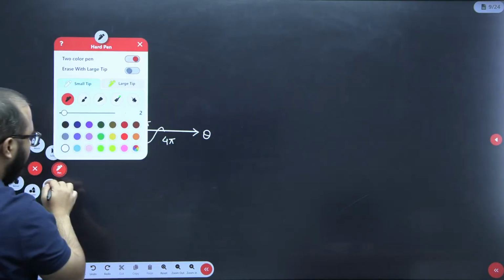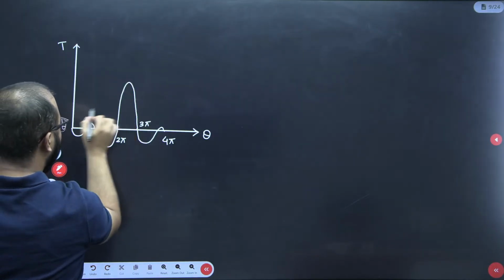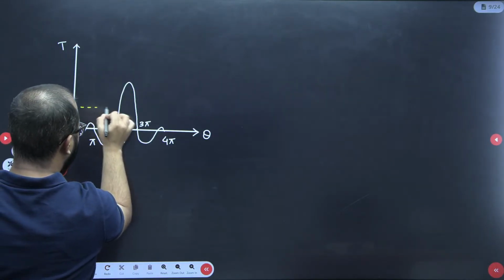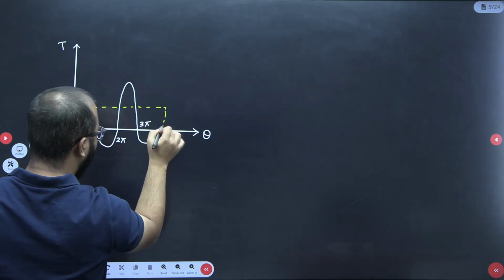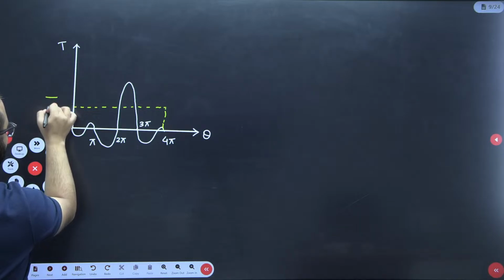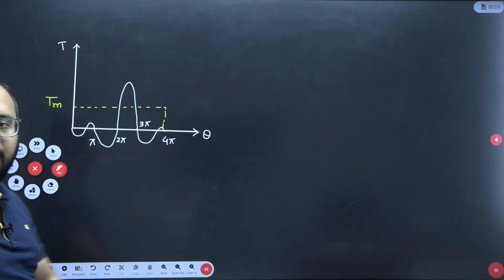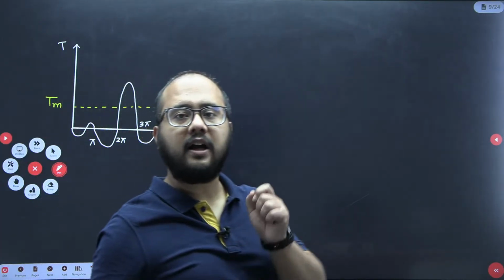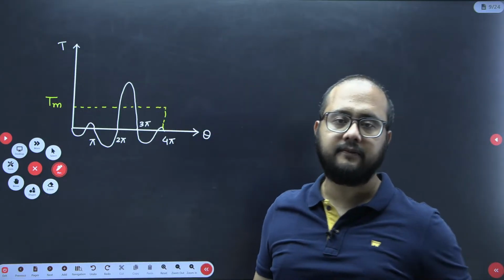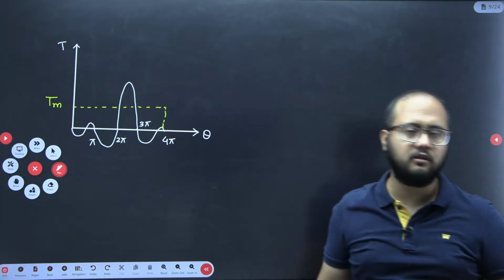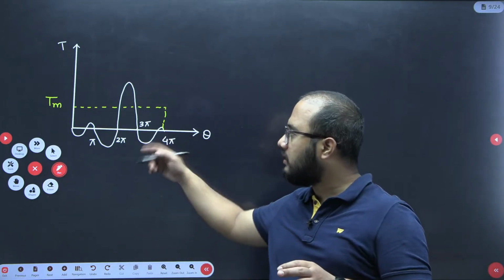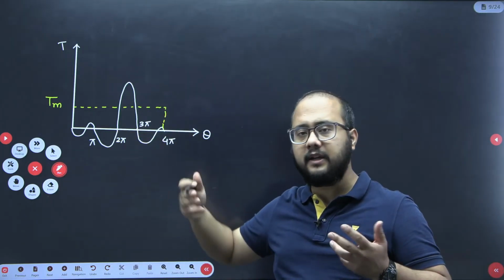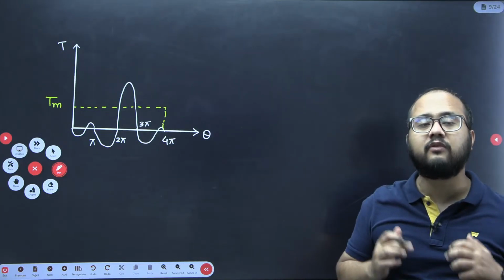Now here you need to understand that we have also mentioned the mean torque value. Mean torque is that torque which is required to just overcome the load on the engine. Mean resisting torque also we can say. Now if actual torque is more than the mean resisting torque value, in that case what will happen?